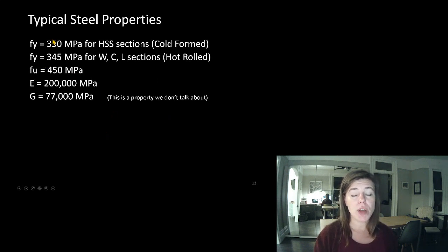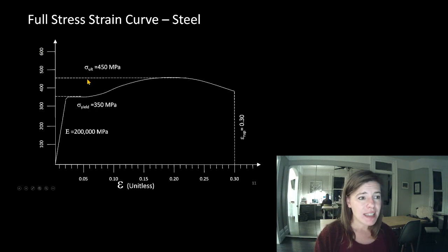So as much as we're talking about 350 MPa steel, for a cold section, our FY, or our yield stress for steel, remember, we don't want to go past that. That's as much as we have this maximum up here of stress. After this point, we're getting really large, ugly, nasty, big deformations that are permanent in our steel. So we don't want to go past this.